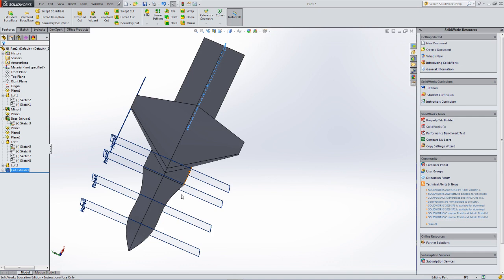from the side. Well, aerodynamically, that means that you have this inlet extending ahead of the wing, and you can't put the inlet right even with the wing because there will be too much distortion as the wing changes angle of attack. So you have to extend the inlets ahead of the wing, and then when you do that, you automatically get strakes, essentially.